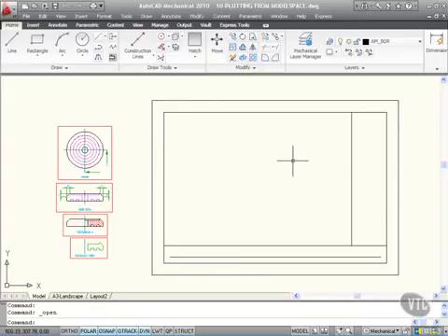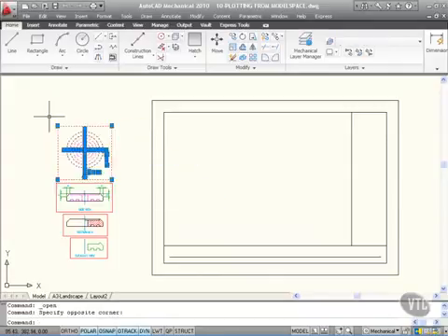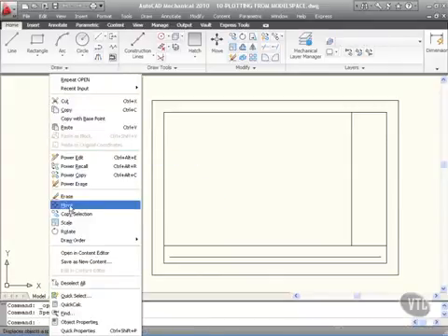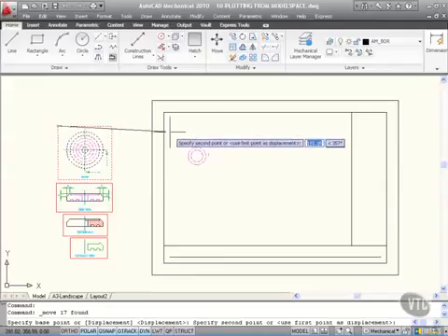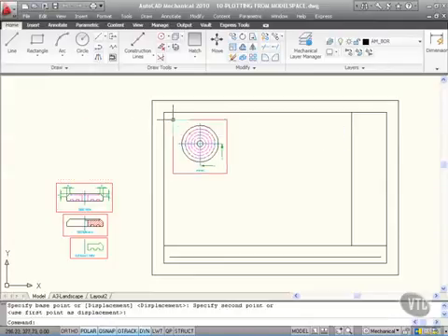So what we're going to do is place these scale areas onto our drawing title block. That's easy. It's just a case of selecting all of the objects that make it up like so, right click, move on the shortcut menu, pick a base point, and I can drop that scale area straight in like that. I'm not actually changing anything. All I'm doing is moving those objects and that scale area to a different place in the model tab. So that will plot at twice its original size, that scale area. I need to be careful there and place these objects appropriately.